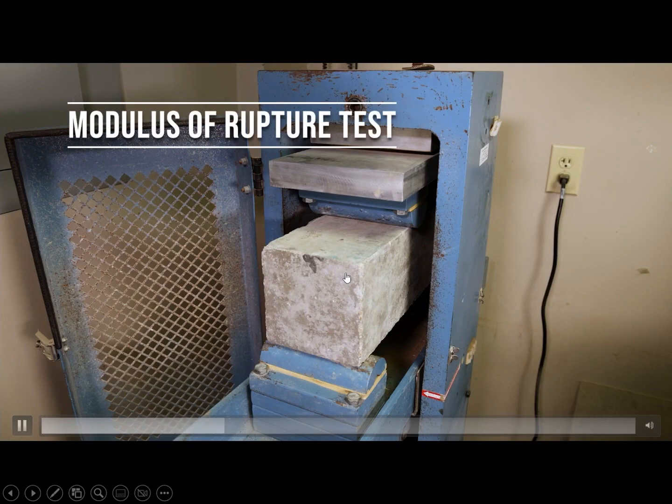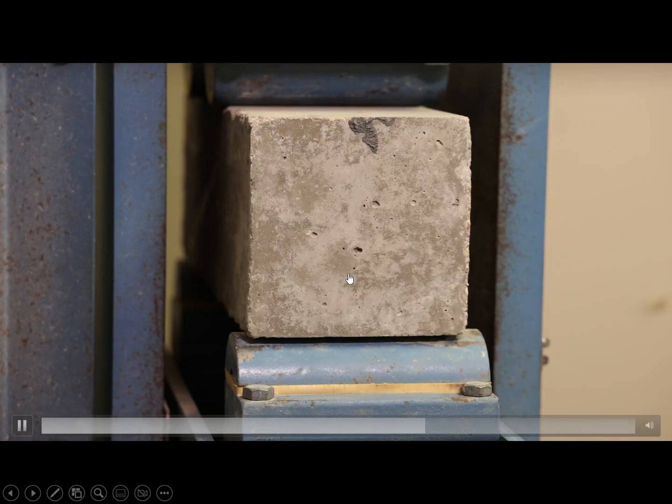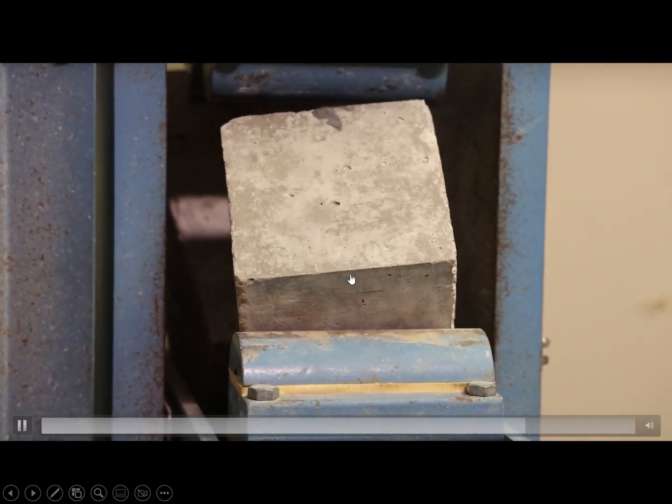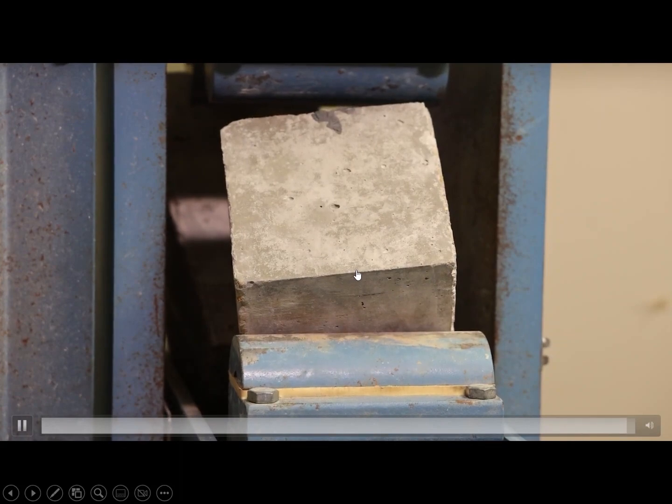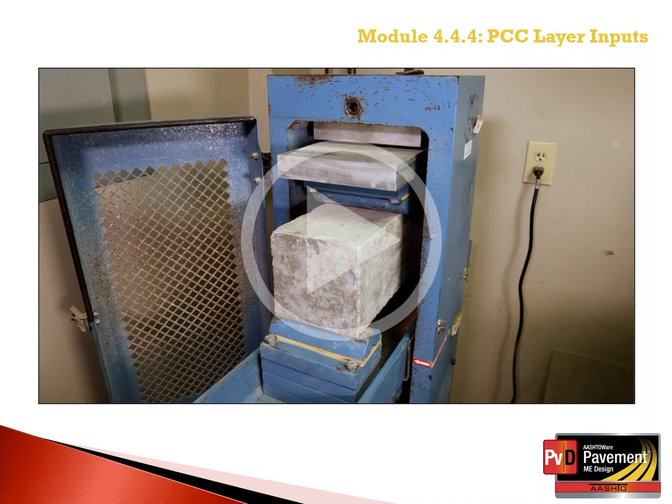The center of the specimen, showing the failure, could not be shown because of the specific test setup. The PCC modulus of rupture is used to estimate the allowable number of load applications of the PCC layer for predicting fatigue or mid-slab cracking. And we will get into that transfer function specifically in Module 5 on rigid pavement design.